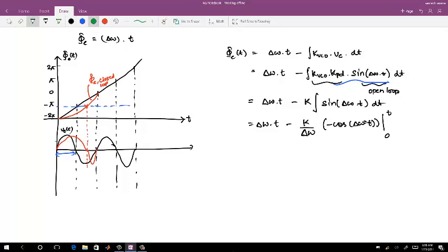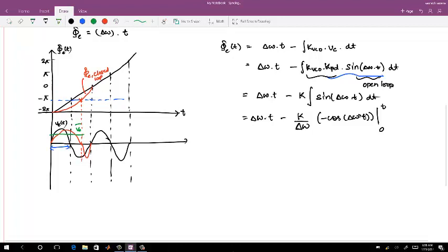So let me say the new average voltage which will pass through the filter is some, let's say, VE average, right? Now this VE average develops as a DC voltage which will bring the frequency of the oscillator closer to the input frequency. So this is how it is going to pull up. It is the voltage which it will develop to get the oscillator closer.